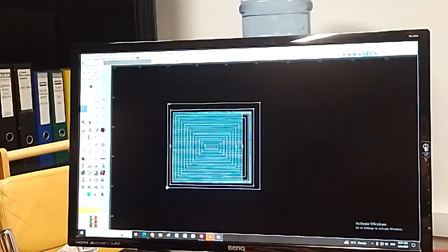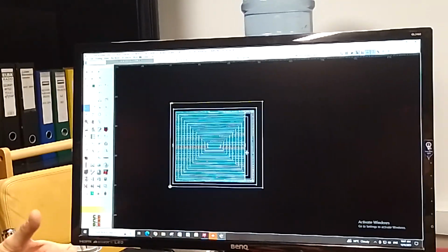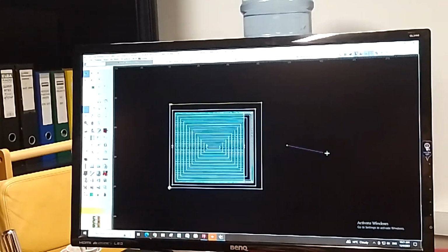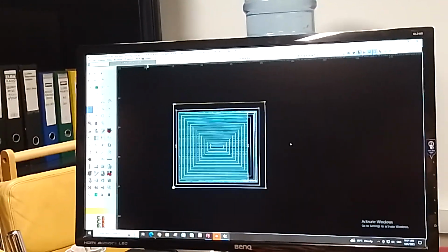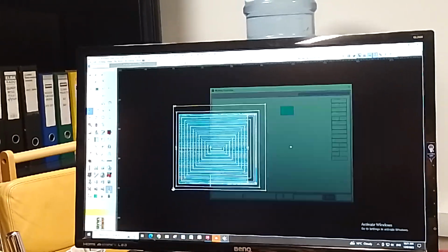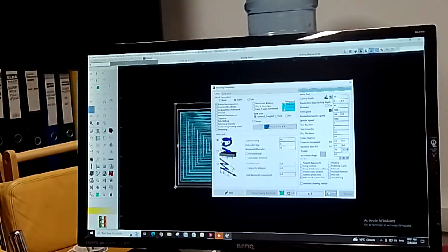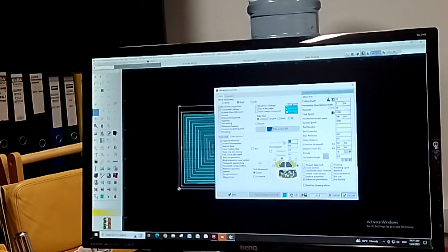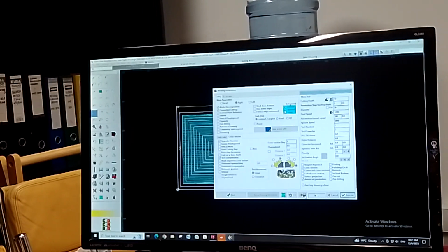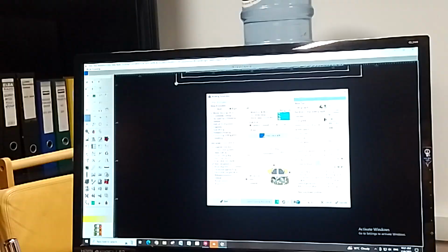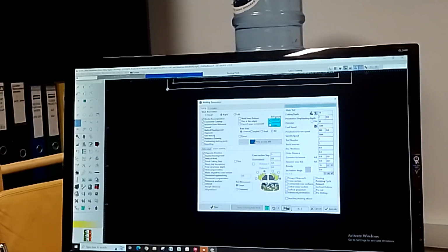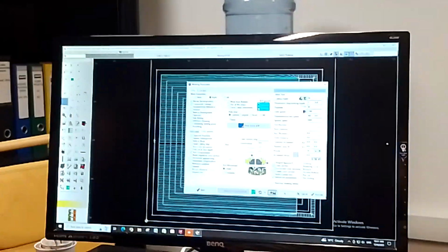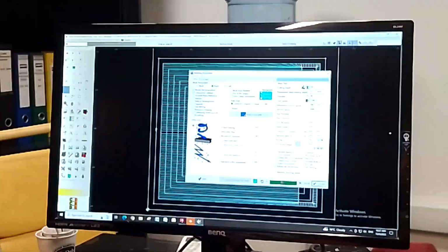Okay. Now I show you a trick to see the material for creating the 3D surface. You can put just a point here and activate here the cross section. Put here value 5. In this case, this button appears that creates your surface. Then I can remove this.